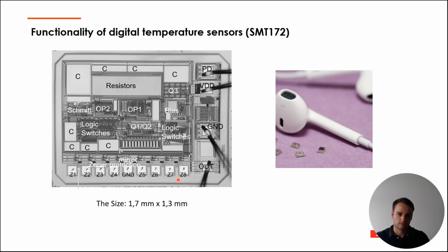calibration on a wafer. But first of all, I think the temperature sensor is really special because it's based on a 0.7 micrometer CMOS process, and the sensor is using a BJT transistor to generate a duty cycle as an output signal. And like I said, a duty cycle as an output signal is really rare for a temperature sensor.